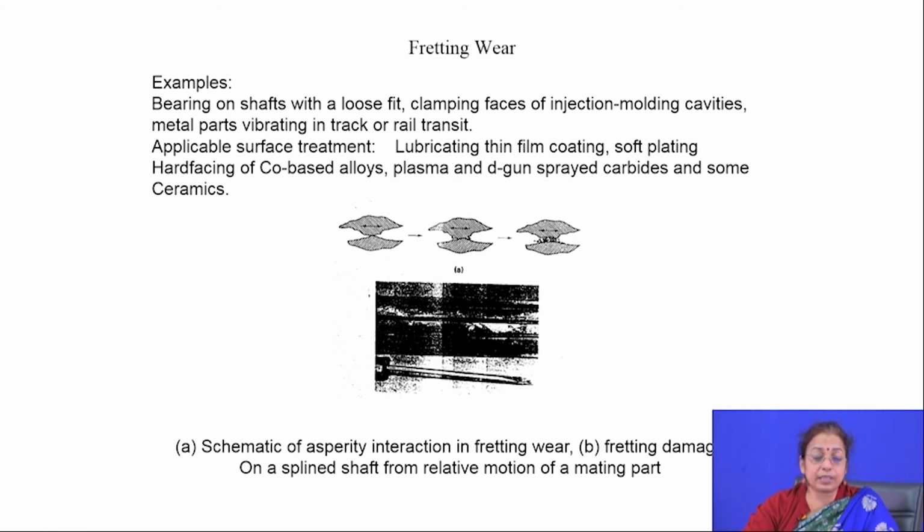If you think of material failure by adhesion, usually the hardness difference is minimum. The probability of adhesive failure increases when similar materials are moving over each other instead of dissimilar materials.